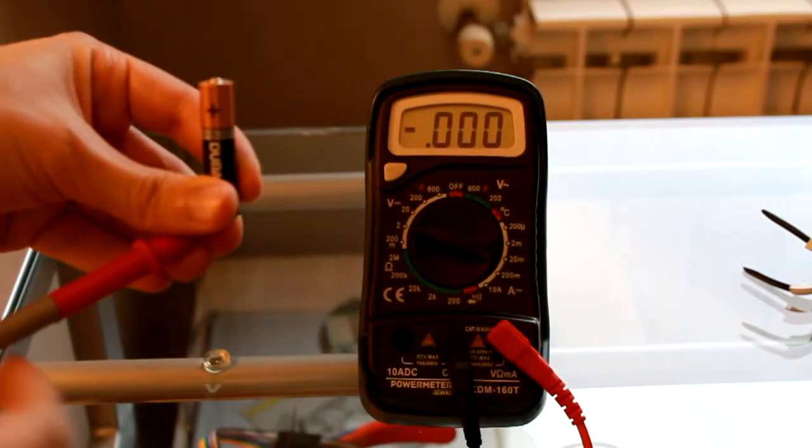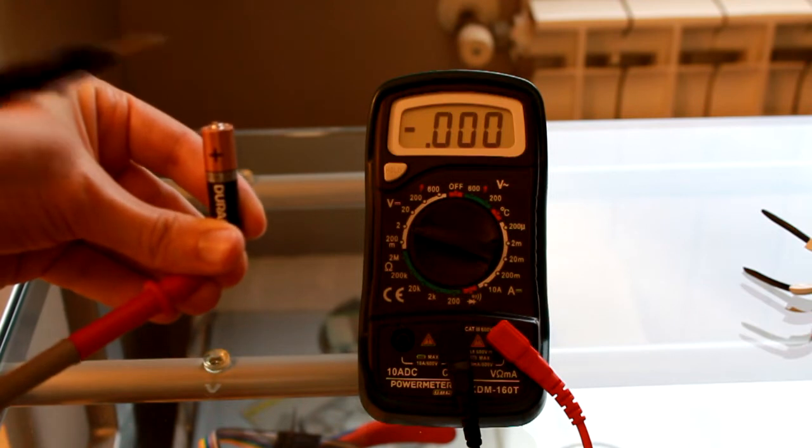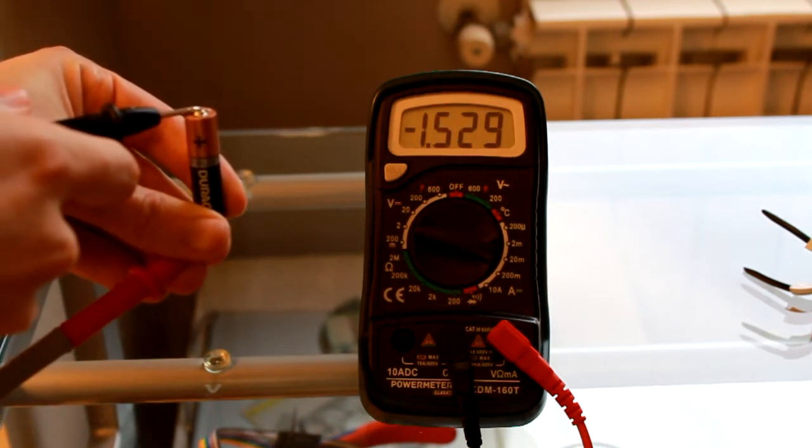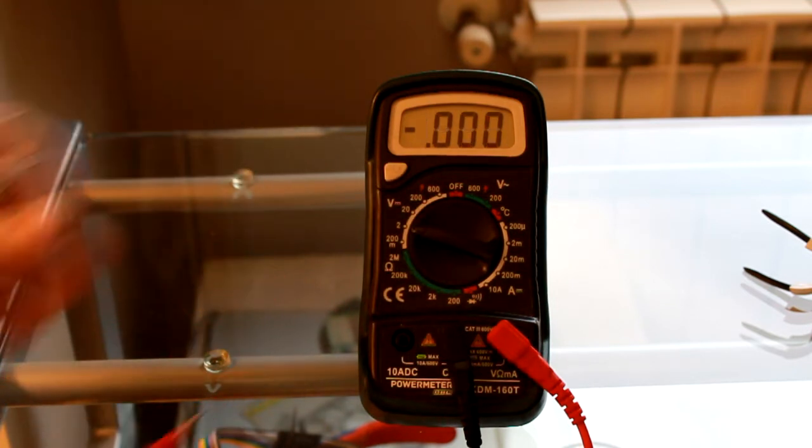What happens if I try to swap the 2 probes? Will something break? Will the universe stop existing? No, I just get minus 1.5 volts. And that is a thing. It really only means that the voltage on the red probe was lower when compared to the black probe. So the charges on the red probe had less energy than the charges on the black probe.